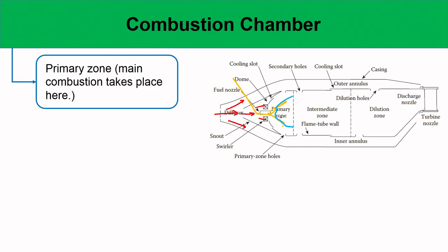So if you just summarize the processes, you have got the liquid atomization. Atomization means the breakup of the liquid sheet into small droplets. There can be primary atomization, secondary atomization, and so on, where big droplets go into small droplets. So then these small droplets must evaporate.